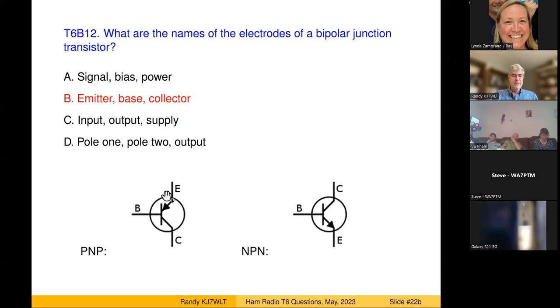And the symbol for this kind of transistor in a schematic diagram is the circle, again, with three lines coming in, and with an arrow going in or out of one of the internal lines. But mostly you just have to remember that anything that looks sort of like this is probably going to be a transistor in a schematic diagram. And for this particular bipolar junction transistor, you just have to remember that it's emitter, base, and collector.